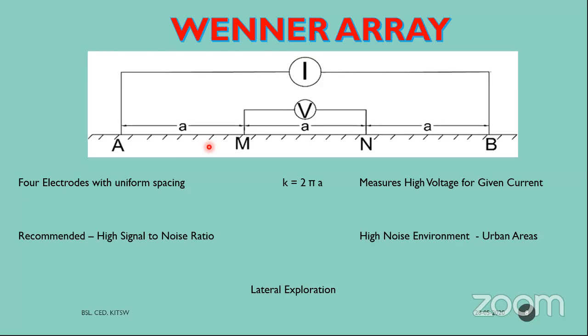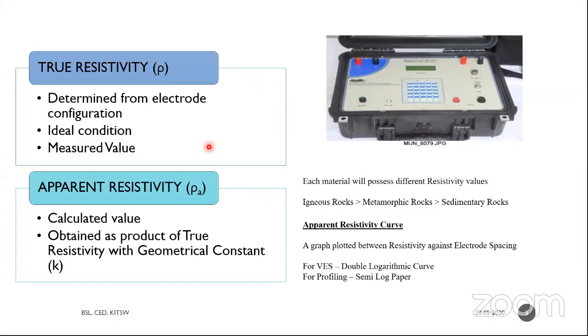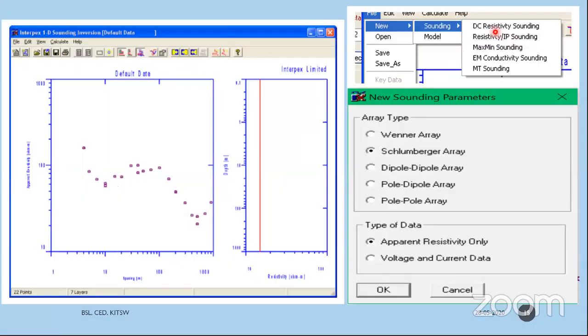Especially I want to tell this point at this time, because the trend has shifted. The software itself has something called DC resistivity sounding. But some equipment, such as in the US, will provide AC current also, but with a low frequency. So this test can be done using DC current as well as low-frequency AC current. Regarding the precautions, I personally recommend referring to the ASTM code, in which everything is described in detail.